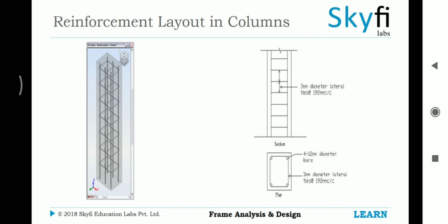As in the case of beams, reinforcement is also provided laterally, called lateral or helical ties. The main role of lateral ties in reinforced concrete columns is not to transfer the shear stress, as it is mainly in the beams, but rather to prevent the buckling of longitudinal bars and transfer of tensile stresses.